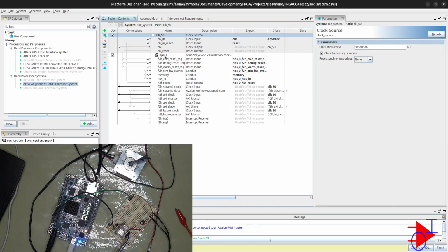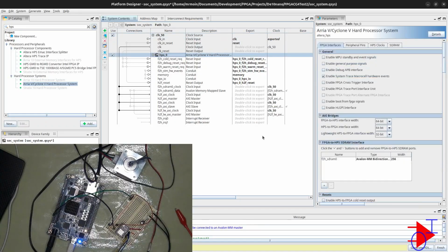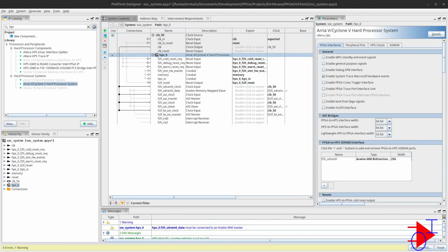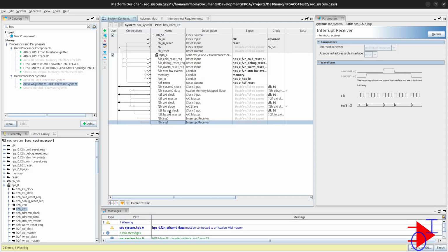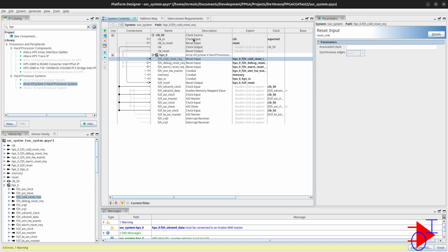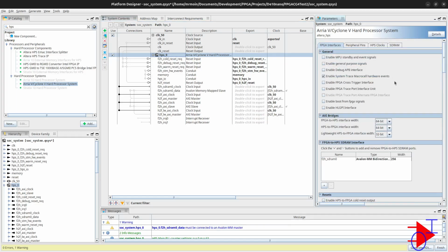And let's see what we can do here. Okay, another thing we want to do is remove all the other items from here, like interrupt requests. There's no need for that. AXI clock, I don't think I need that. I may have to check my test configuration. For now, what I will do is keep these. Hardware events, I don't need hardware events. I don't think I use these at all. I know for sure.